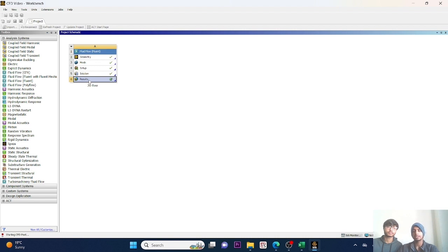To do the grid analysis, we will choose a point in the planar body and see the velocity at that point for different mesh sizes, and we will see the graph of that. We are going to do it multiple times to get the data for multiple mesh sizes.